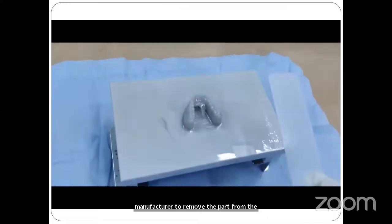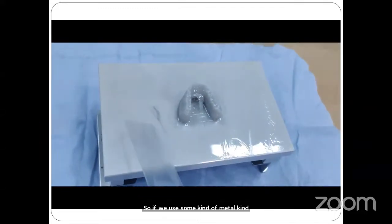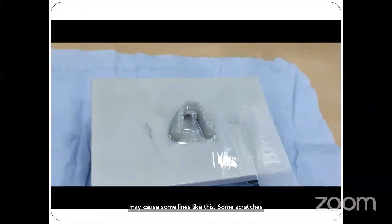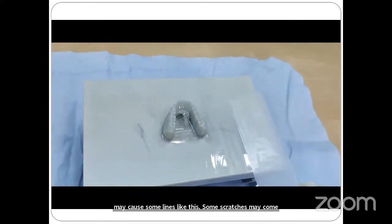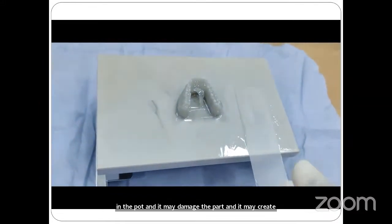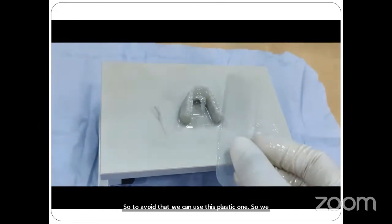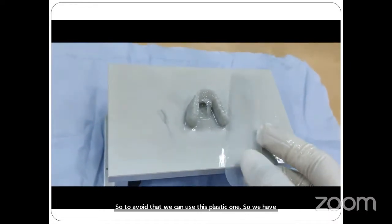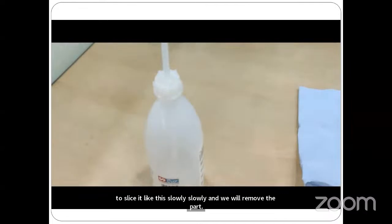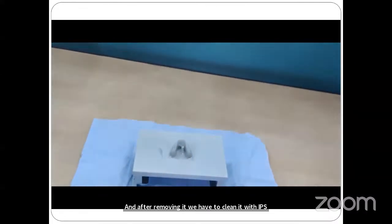If we use some kind of metal tool, it may cause scratches on the part and damage it, and it may create scratches on this build plate. To avoid that, we can use this plastic one. We have to slice it slowly and remove the part. After removing it, we have to clean it with IPA solution, and using these tissue papers we have to clean each and everything.